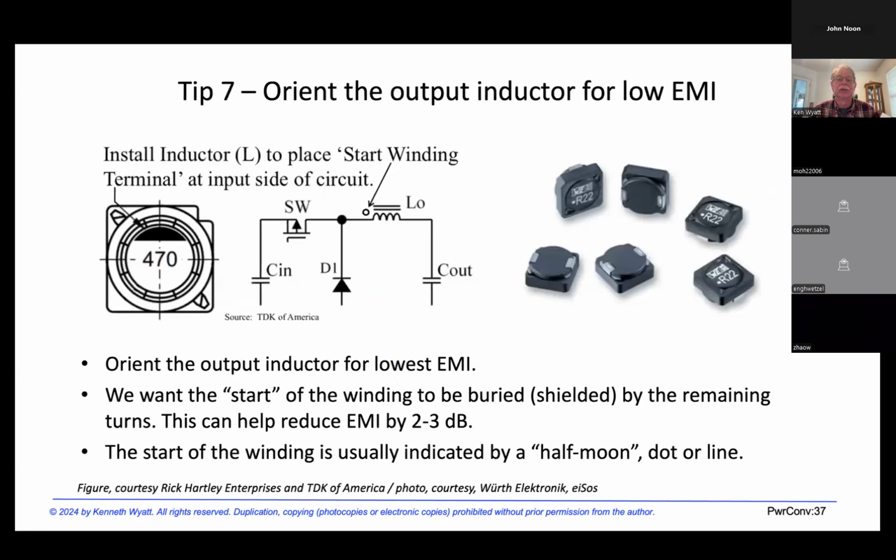Okay, here's a tip that I never realized until I took a course from Rick Hartley, and that is you can orient the output inductor for low EMI. Inductors have a start on the winding and an end on the winding, and the start is usually covered by several turns of wire before it gets to the end. And so if you position or locate the pin 1 of the inductor towards the switch node,